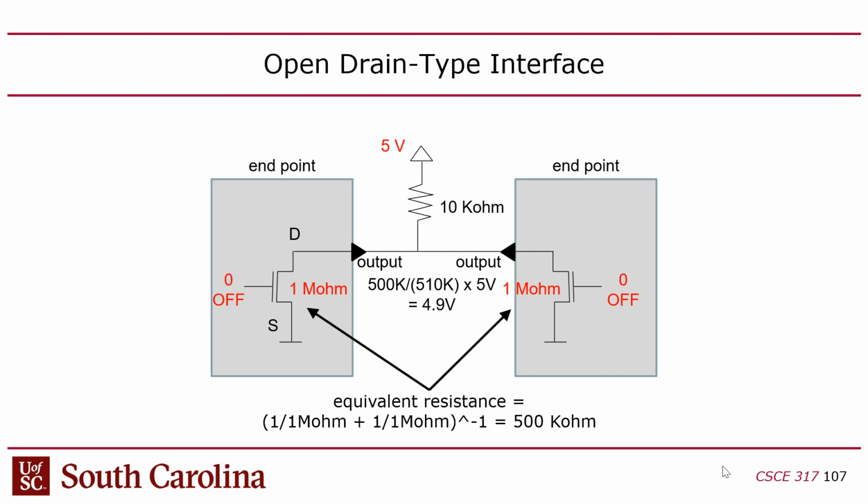Now the disadvantage of this is that you can never explicitly set the wire to 1. 1 is kind of its default value, which it will be set to if you don't do anything, right? So if no one's controlling the wire, it's 1. And if multiple drivers are trying to pull it up to 1 or set it to 1, then it's still 1, right?